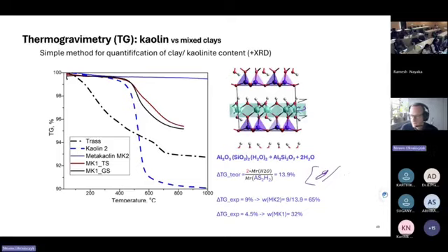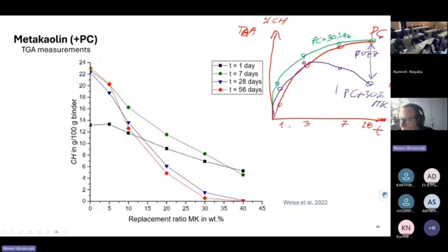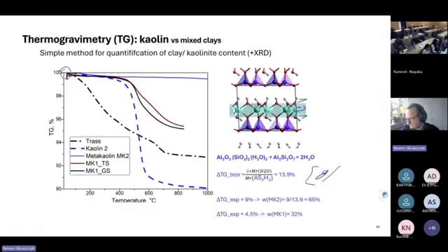So in this case, you get the grams of metakaolinite per gram of your initial sample, your initial mass. So this is a gram per gram of sample, which you put into your TG. So your result here will be gram per gram of sample, initial sample. So this is the unit.